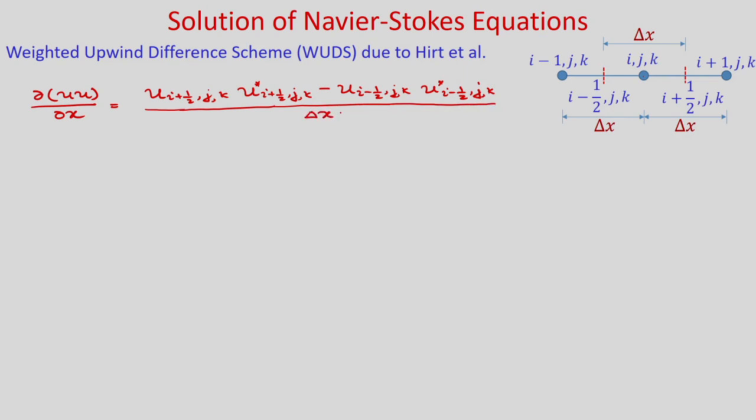So, here at this point we are discretizing this u term. You can see this is the midpoint between i, j, k and i+1, j, k, and the other point is i-1/2, j, k. The distance between these 2 points is delta x, but for the velocities we are writing u(i+1/2, j, k) and another star quantity, u star.